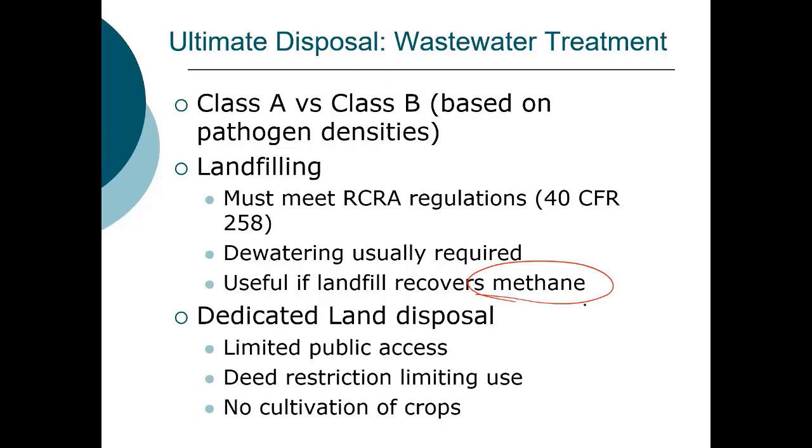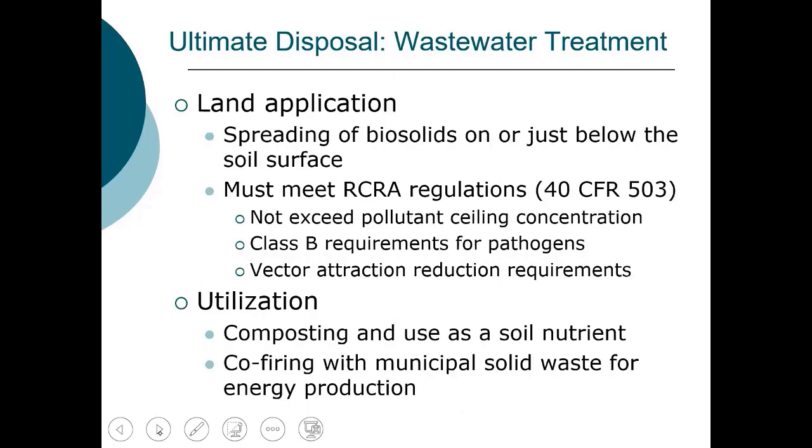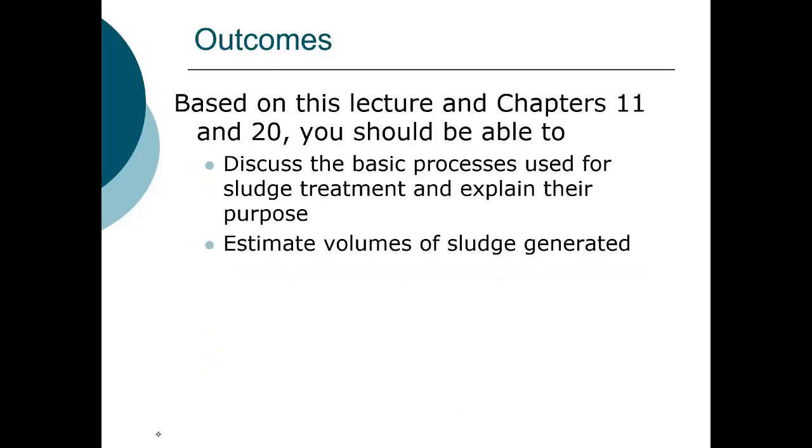Or it can be used for dedicated land disposal. Again, one needs to be careful there and make sure that there's limited public access. There are restrictions as far as cultivation of crops and how that land can be used. And I mentioned a little bit the other day with Lapeer the disposal of the sludge from their plant and challenges with PFAS. So hopefully this gives you a sense of treatment